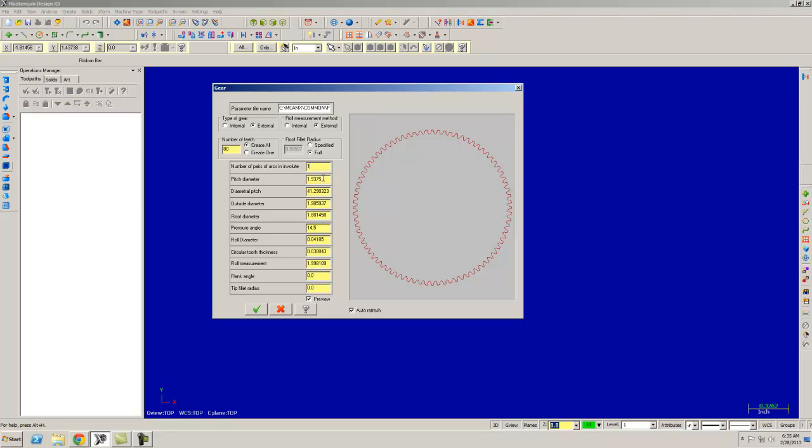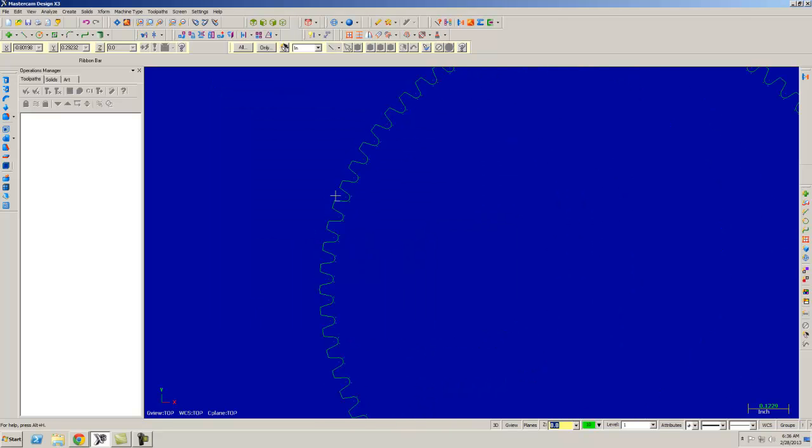The pitch diameter is 1.667. Now the diameter, this is probably going to be rounded up, so I want you to put, this is really important, to put 48. All right. So the OD is 1.7, so we're going to put that right at 1.7. And then basically the rest of this stays the same. And then accept that. All right, put a full root diameter in there.